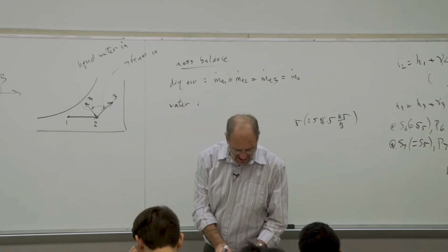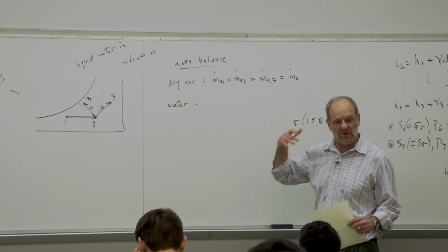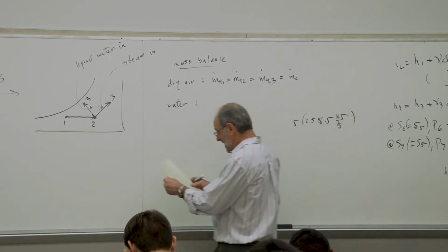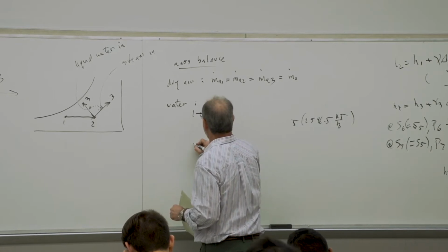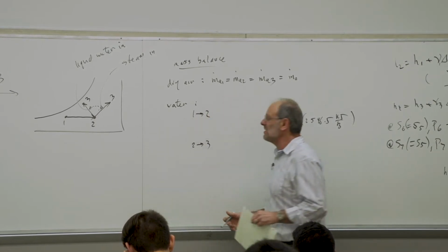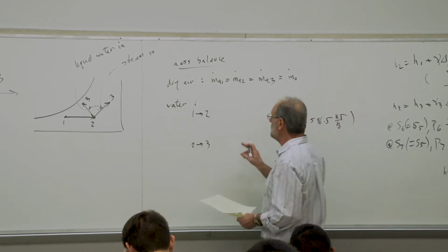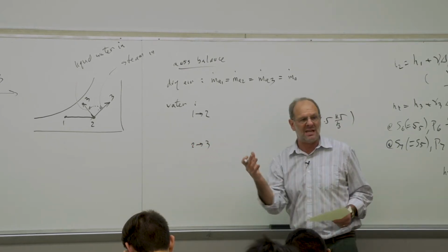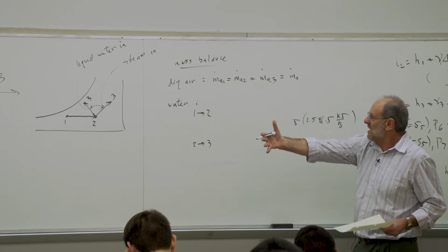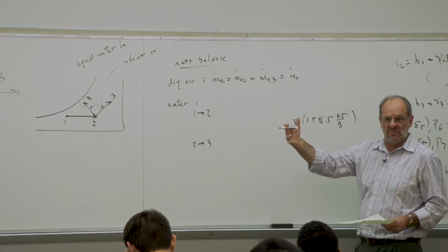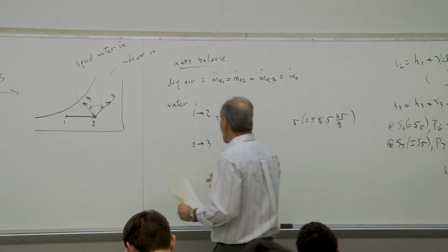Next, we would have our energy balance term. I'm sorry, not energy, that's next. Next, we'd have our water mass. Now here, we would note that there's really 2 processes, from 1 to 2 and then from 2 to 3. So we have to identify each one separately. We would note that from 1 to 2, we're not adding any liquid water or water vapor. We simply have however much water vapor was in the air coming in at 1, and then that would have to equal however much water vapor is in the air at 2.